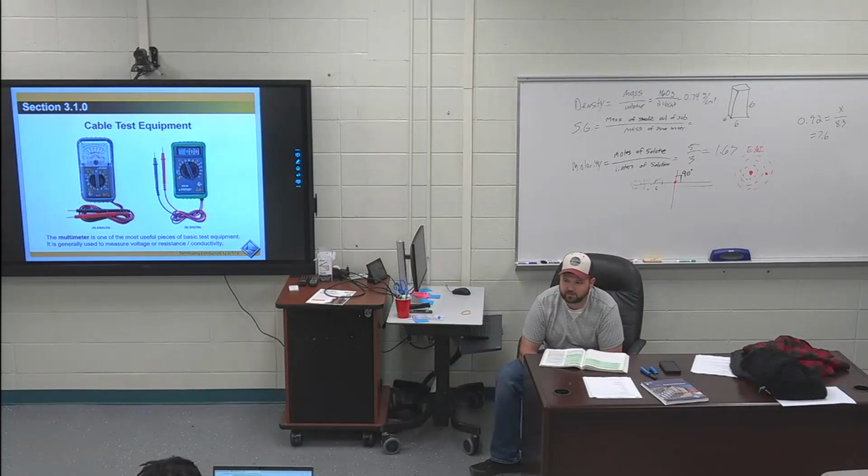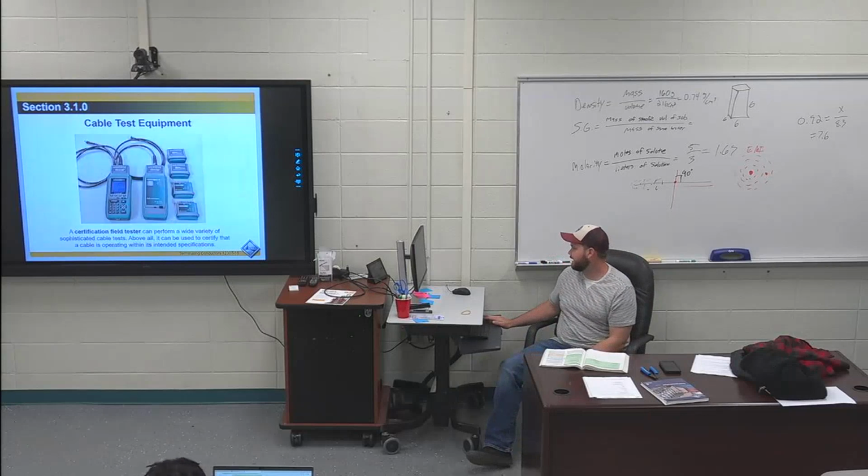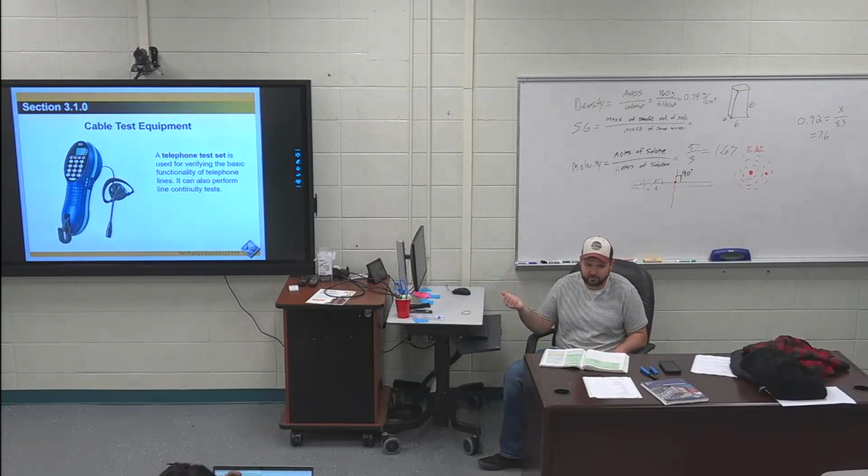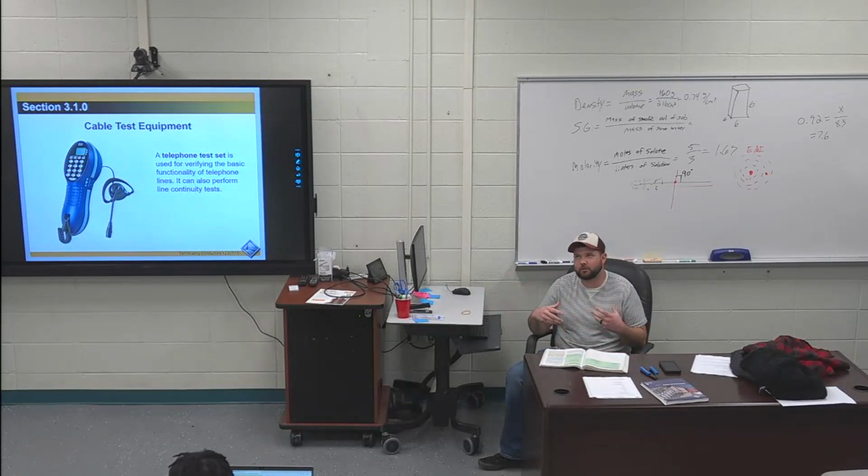So what ringing out a conductor means is, say I have a cable with 10 leads, or 10 wires in it, and that cable runs out from a control room out into the plant somewhere, but the wires aren't color coded, or it's so old you can't tell what color they are. They're numbered, but a lot of times the numbers fade off, or as soon as you touch them, they wipe off. So ringing out a conductor is having you on one side. You can do it by yourself, it's a pain, but it's easier with two people.